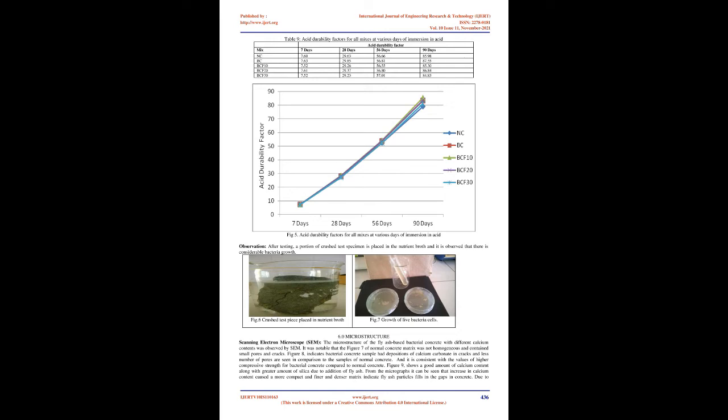The specimens were immersed in 5% H2SO4 and HCl and readings for weight and compressive strengths were recorded for all mix types at 7, 28, 56, and 90 days. The solution was replaced at regular intervals to maintain constant concentration throughout the test period.